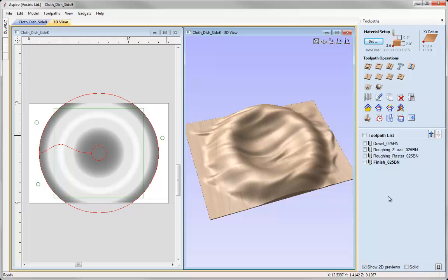Now on this side, when we machine the dowels, what's important is that we realise that that's going to be done when there's no material there. So again, we imagine we've machined the other side, we've taken our piece of material off, and the first toolpath we're going to output on this side is just to drill those dowel holes or profile those dowel holes into a sacrifice sheet, either into the sacrifice sheet attached to your machine